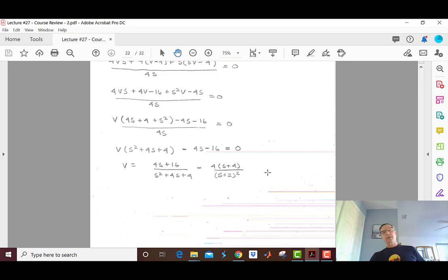Final value theorem's weird because the value at t equals 0 is going to come from substituting s equal to infinity. Well, time and frequency are inversely related. That's another of the trapdoors that I love so much about EE310. Bottom line, you want to know this value at time equals infinity? Use the final value theorem.